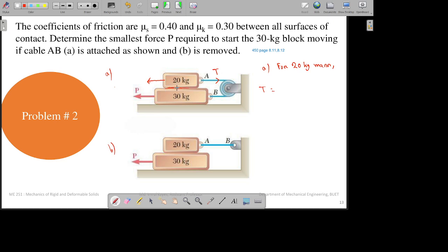In this surface, friction will occur. So you have to find out first the value of N. N will be mg, right? The mass of the body is 20 kg, so m will be 20 multiplied by 9.8. So that is our N. Now you need to know the value of mu, which is the static friction, because it is not in motion yet. The motion is going to just impend. So 0.40, which comes out to be, let me again use my calculator.